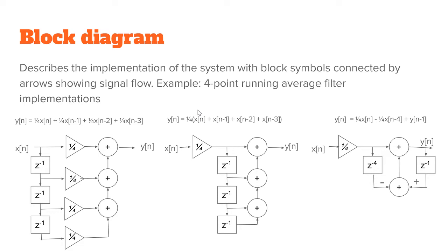And while in this difference equation this multiplication should be done separately for each term, on real code you would just have the one multiplication of the input signal. Some deep memory to remember some of the previous values. So this is the history of the fourth previous value, and then a 1 time step delay. So you just need to remember what was the previous value on the output. Okay, quite efficient.